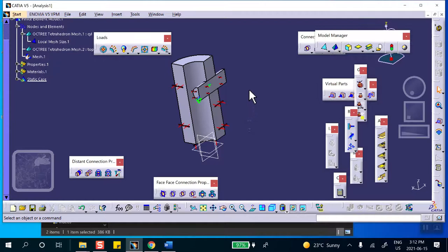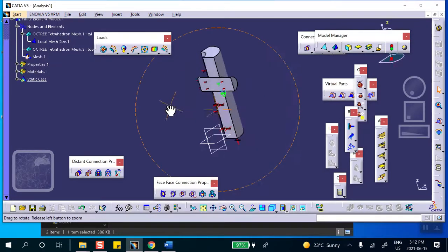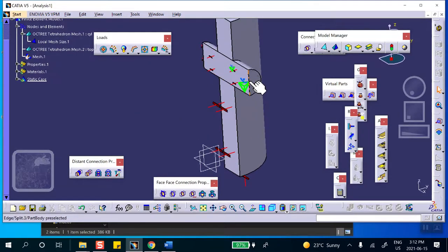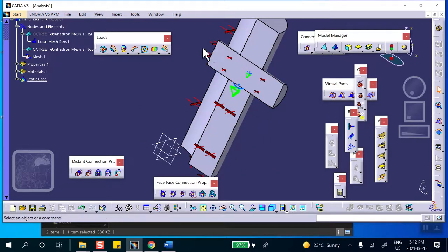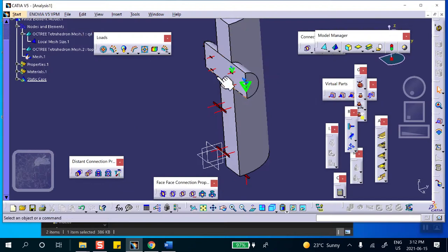I know it's unfortunate, but that's the way it is. Now, as far as pushing this thing up, notice that we don't have the issue of this pin turning here or coming out, because there's a surface slider there, there's a surface slider there. It won't be able to rotate. It won't be able to stick out. So all we do is the user-defined restraint.